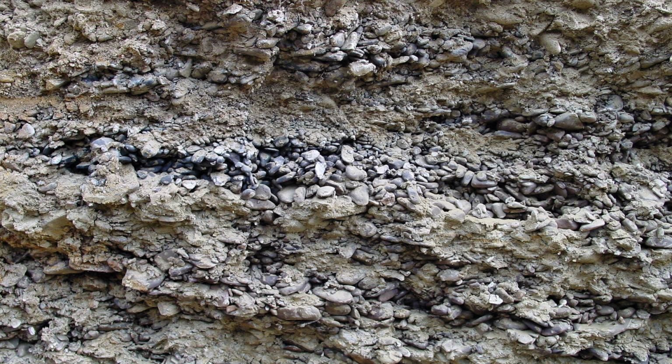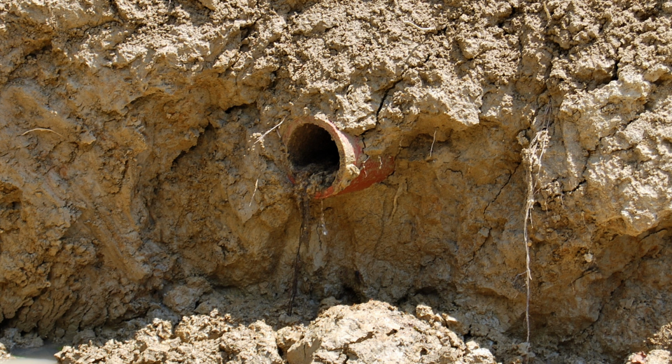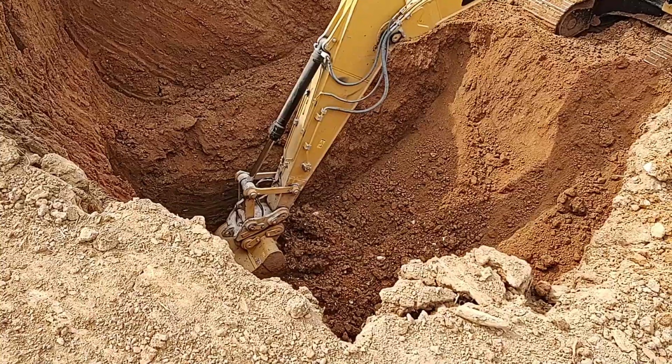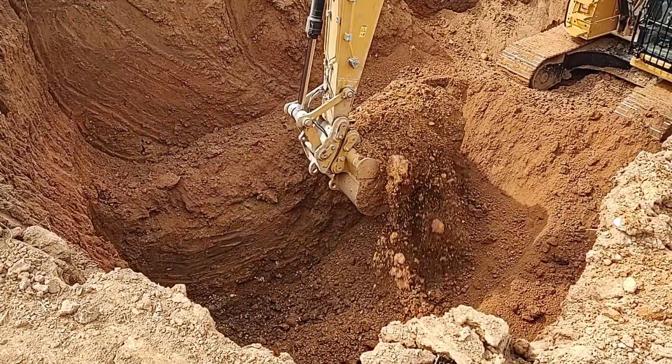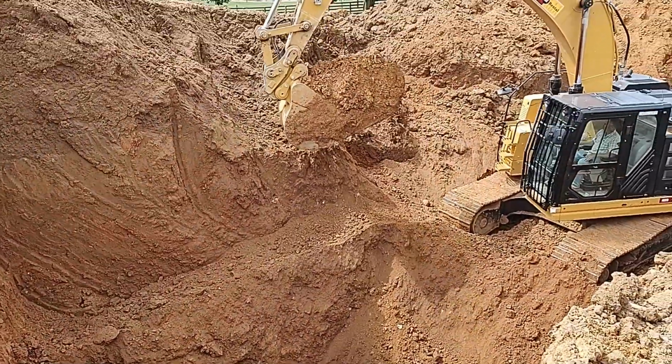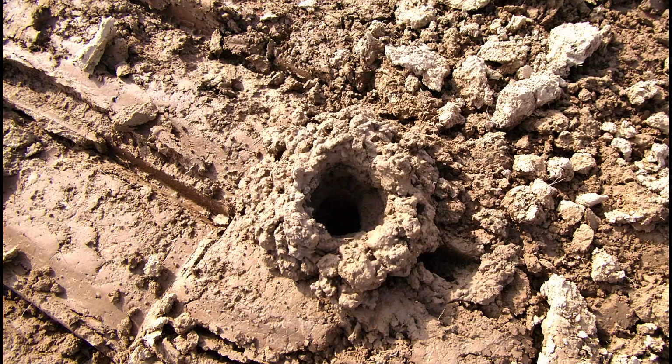Well, here's a real problem. The thick layer of gravel was exposed when we were digging a core trench for a groundwater dam. The gravel was shaped like a stream channel that had been buried years ago. There is no way the wetland would have held water without building a groundwater dam at this location. Water is flowing in this buried clay tile line that we cut while building a groundwater dam. It's often necessary to dig quite deep to remove gravel when building a groundwater dam. This is why it's important to have an excavator on site that weighs at least 48,000 pounds with a minimum of 138 horsepower.